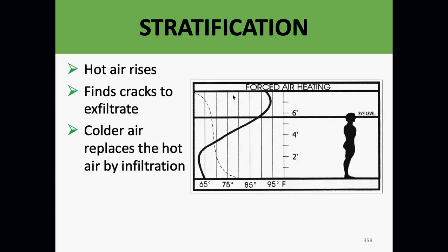That means leave the building. The cold air replaces the hot air. So all of a sudden I'm going to be sucking in through cracks and crevices or through the floors from the basement, and everyone's feet is going to feel cold because the hot air is all exiting the top of the house. That's stratification. It's also called stack effect.